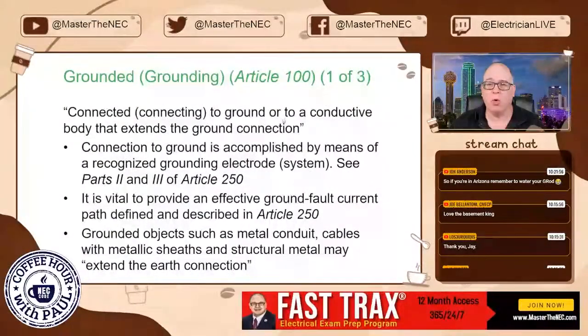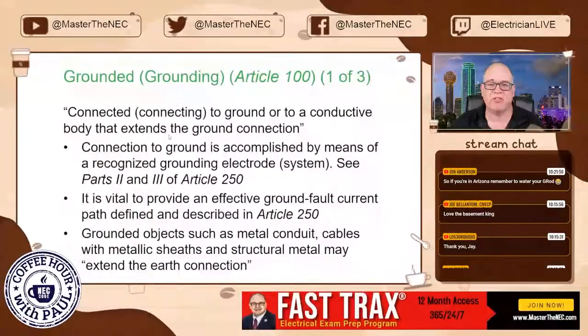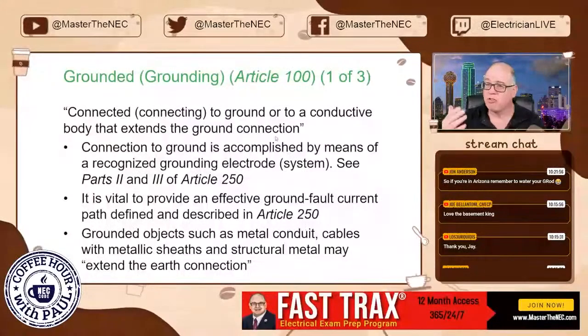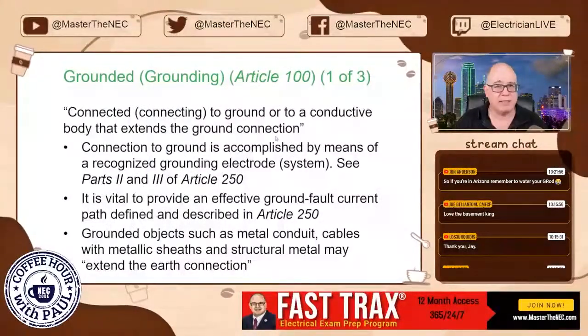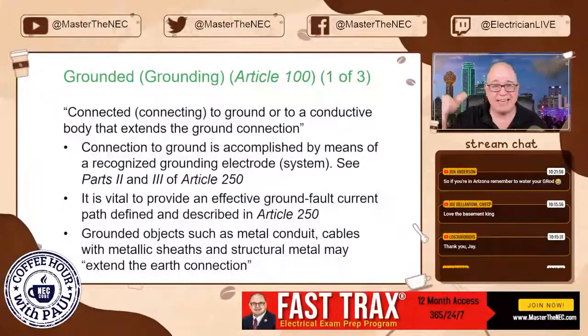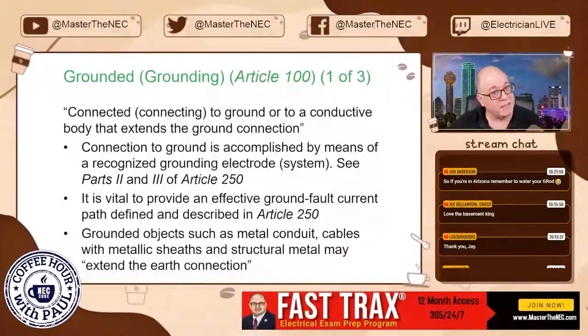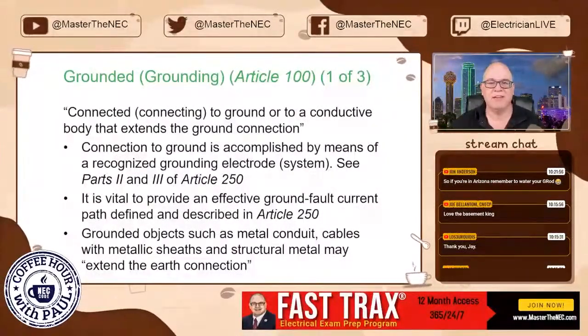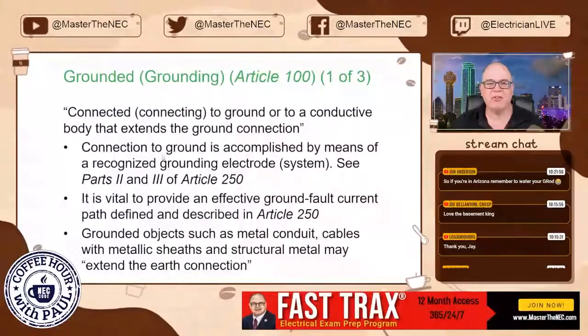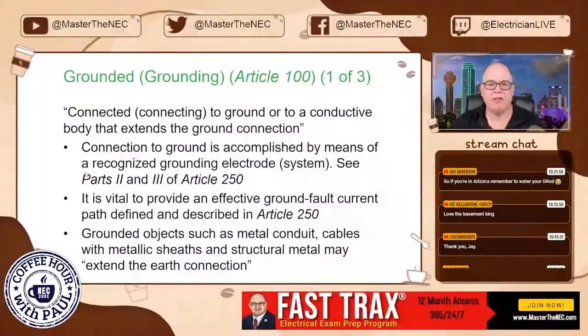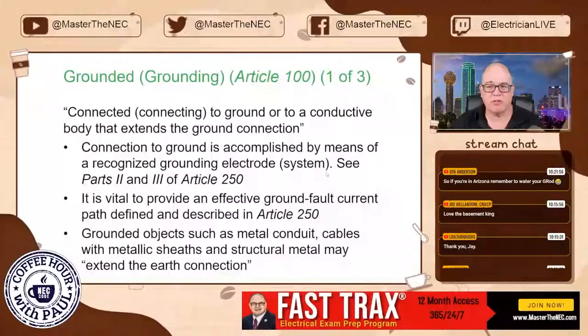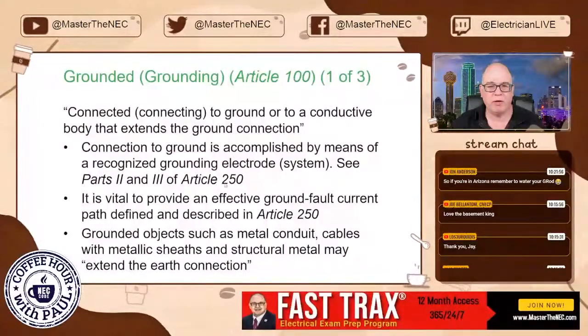Connecting to ground or to a conductive body that extends the ground connection. So even that equipment grounding conductor extends that connection to the 27th floor, right? It extends it. So connection to ground is accomplished by means of a recognized grounding electrode system. See Part 2 and Part 3 of Article 250.